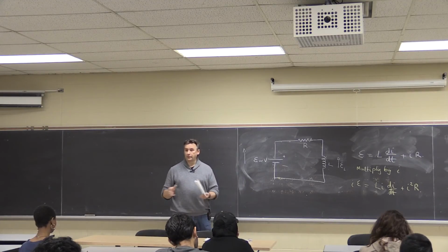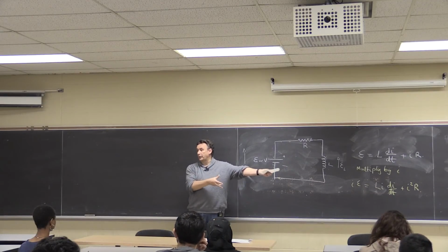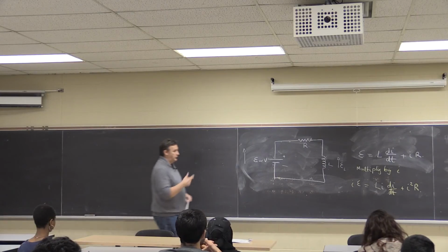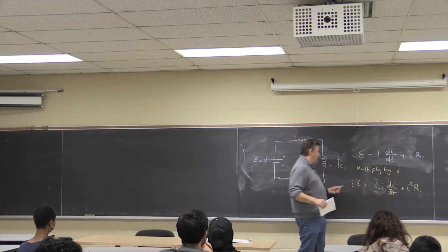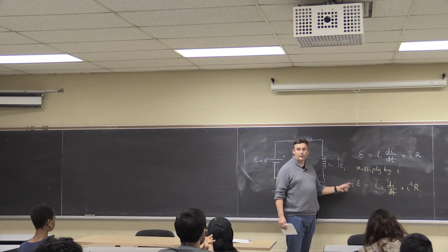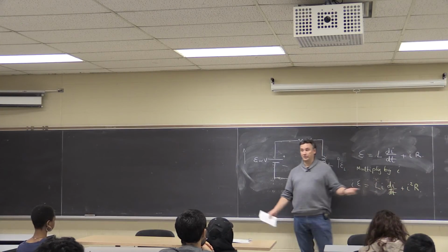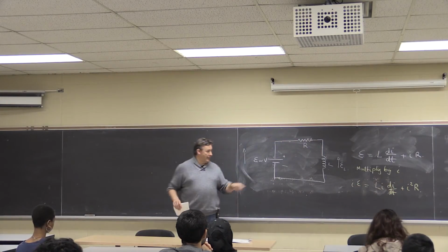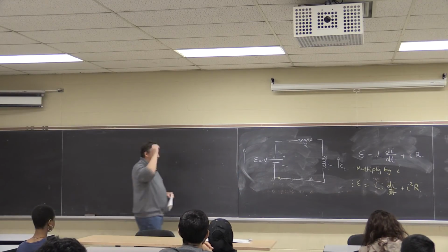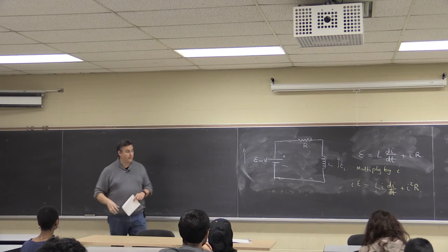Okay, does that help us? Any equation, if it's a true equation, I have to say x apples equals x other apples. So the dimensions on both sides have to be the same. So the dimensions of each of these terms have to be the same. So what's voltage times current? Power. That's true. I squared R is also power dissipated in the resistor, so that looks good. So that tells me that that term, L i di by dt, must be power. It's basically the amount of power stored or the amount of power dissipated in the inductor.